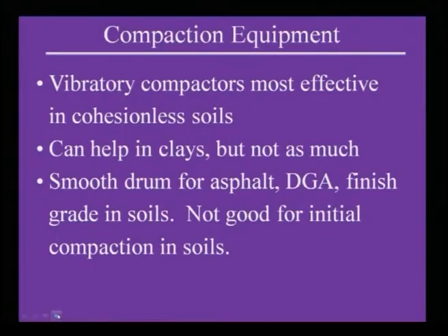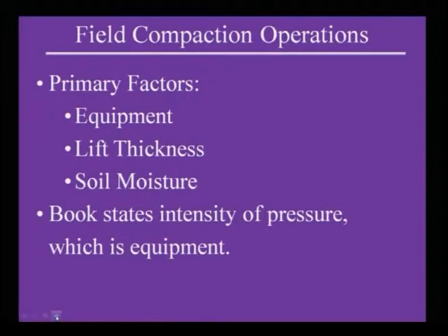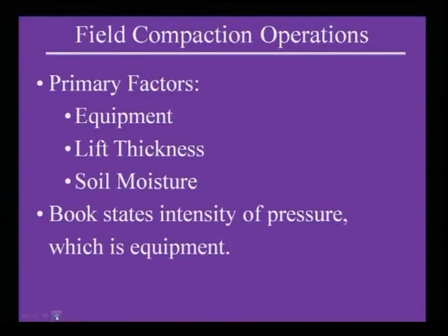Smooth drum, as I said, is for asphalt. Asphalt means road construction, for finish grade in soils. It is not good for initial compaction in soil. Look at this differentiation: which compaction equipment you are going to use depends on what kind of soil and what kind of compaction. The primary factors are equipment, lift thickness and soil moisture. These particularly affect your field compaction operation.